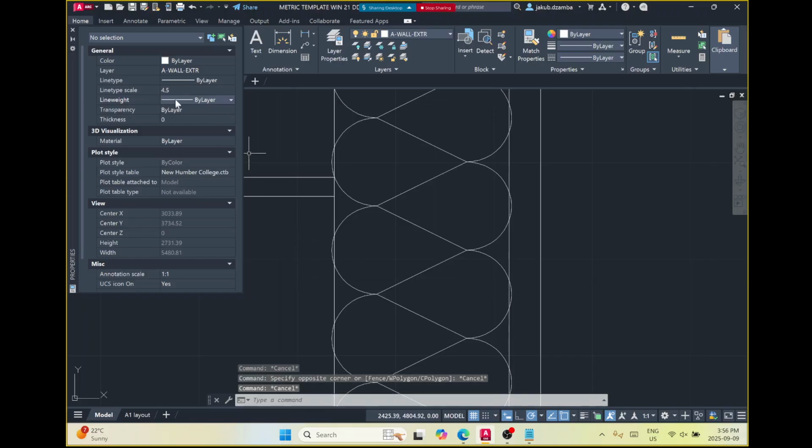Okay. For you guys, is it not giving you any decimal places? Like, does it just give you whole numbers? For the line type scale? I have decimals. You got decimals? So if you have decimals, maybe go for 4.5 or something like that. Or whatever. Play with it till it gives you the right size. If you don't have decimals, you can type in units and hit enter.